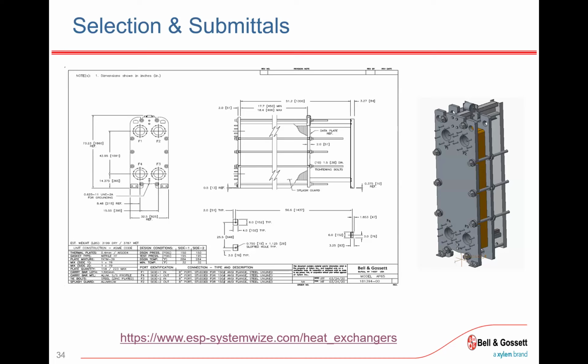Unfortunately, the PLEV is based off of the hydraulic efficiency, so just the pump, not factoring the motor, at least in the software. And so in the future, I'm sure that what they'll do is put a placeholder or an assumption for the motor efficiencies, and in doing so, they'll then be able to use units that have integral drives. Right now, integral drives wouldn't be able to be on the same.